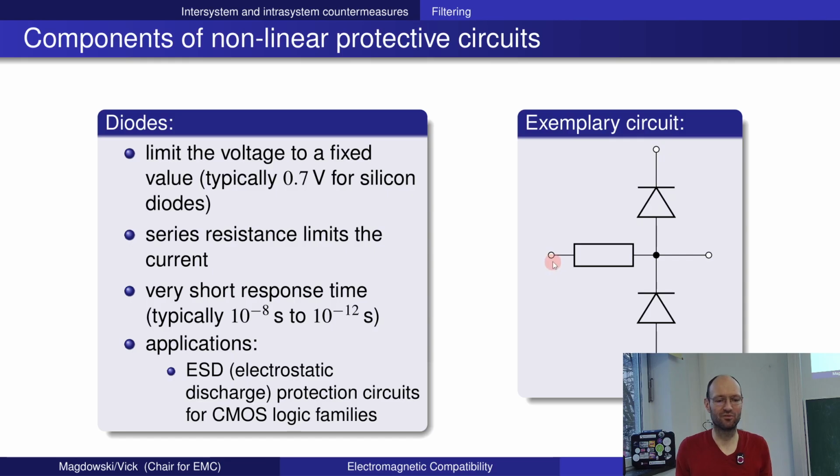So there the challenge is you can put them directly on a chip if they need to have a high current carrying capacity. If they should be able to dissipate a high current, then you need to have a large area on the chip. And this, of course, costs money because it will consume more space on the chip. So there's some trade-off that you usually need to do. But putting diodes against ESD directly on a chip is usually a good countermeasure against ESD.